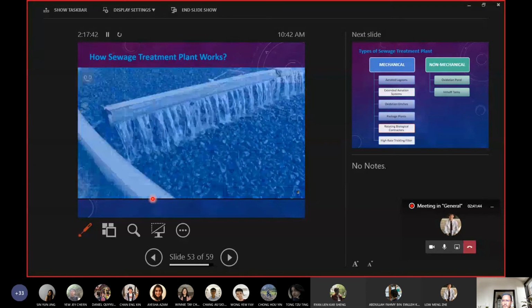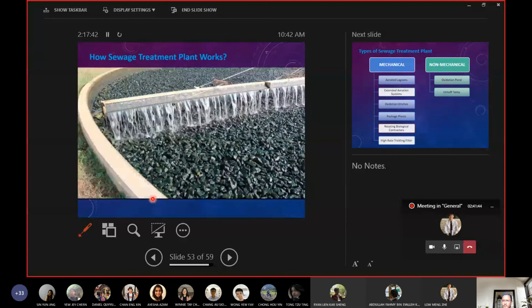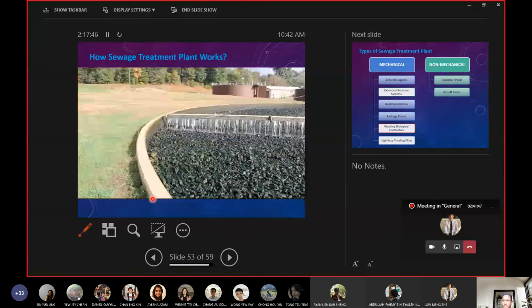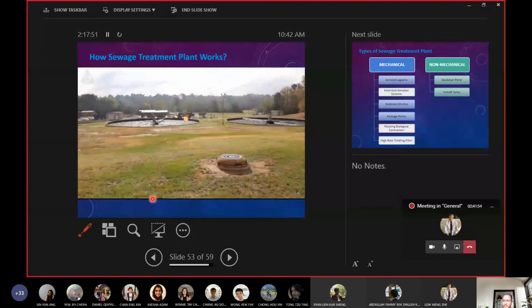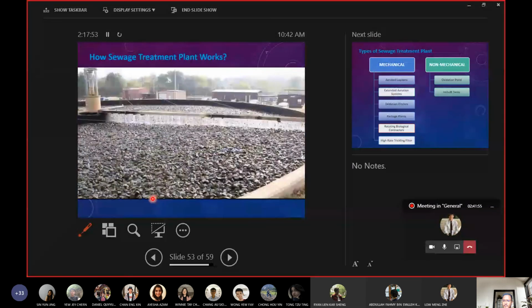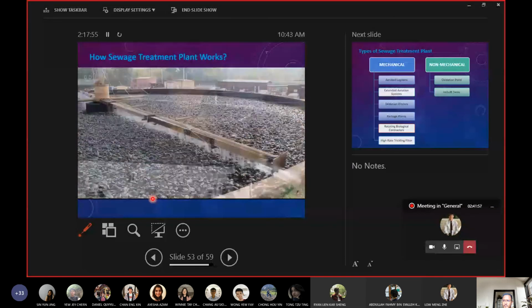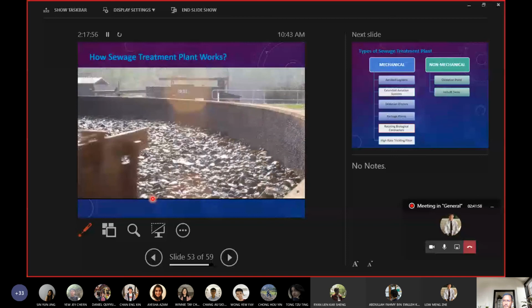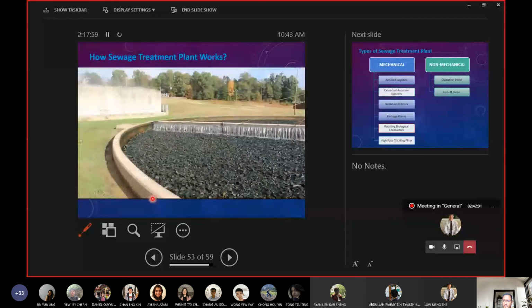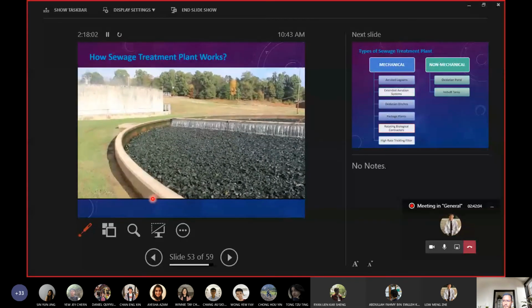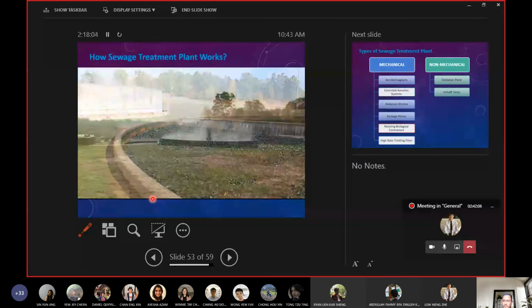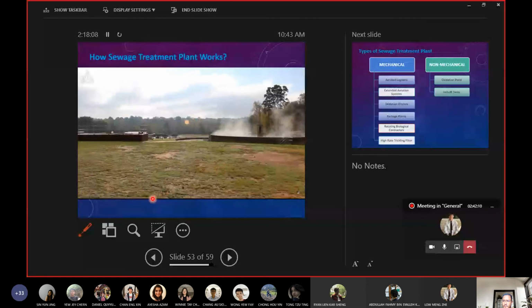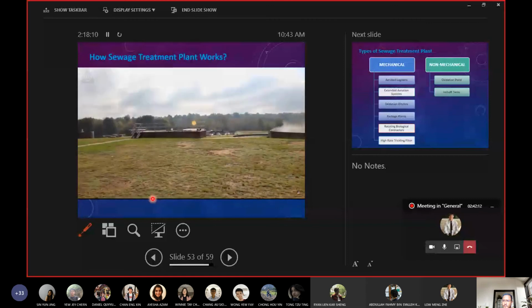Some older plants will add in another step before aeration basins referred to as biofilters or trickling filters. Found in many older plants, these filters essentially trickle the effluent over a medium like stone or plastic, allowing a film of bacteria to chow down on any organic matter in the water. This step is largely not used in newer plants due to more efficient and effective modern processes, but for plants with basins already installed, many still use them because they only benefit the treatment process in most cases.